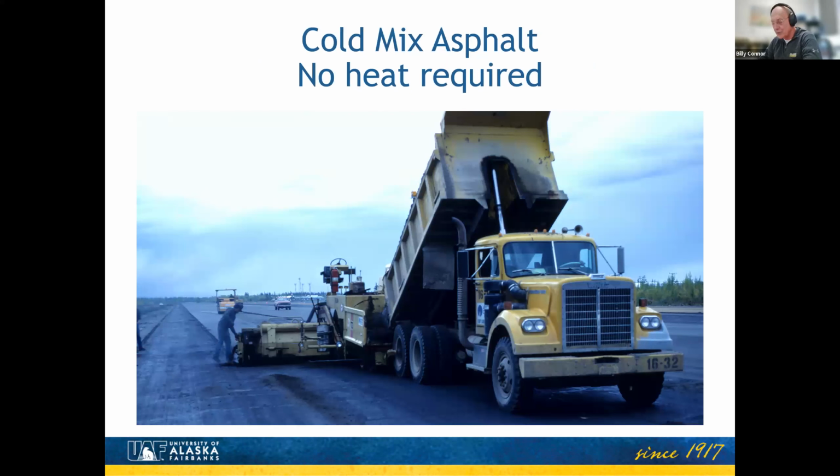I'll also talk in just a moment about cold mix asphalts. Most of you probably have heard about hot mix asphalt. That's kind of the gold standard that people like to use. And the reason for that is once you put it down and it's cooled, probably within the hour, you can put traffic on it. And people really like that.